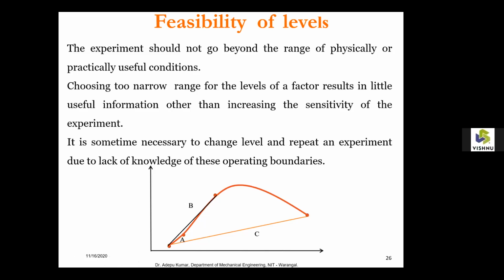So with this, you can get a basic paper of your research work: the effect of each and every variable on the performance, what the maximum range is, why we are not extending it, what the reasons are for not extending, and why you are stopping at a lower level. Suppose somebody asks, why not start from a value lesser than this? Okay, fine. If you apply that, the machining could not take place because sufficient energy is not available. If the energy is not available, your metal is not removed during the machining process.